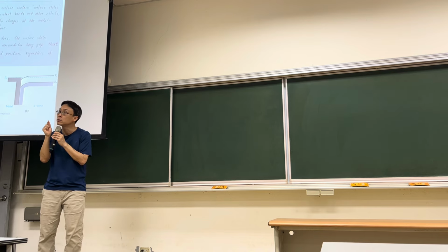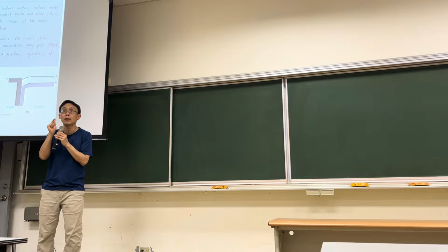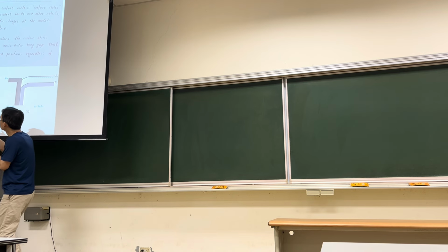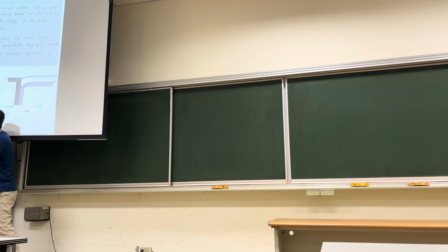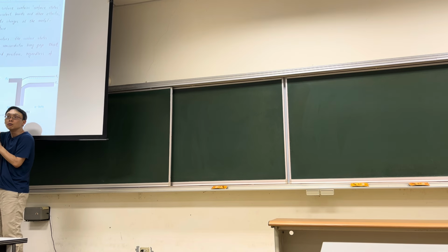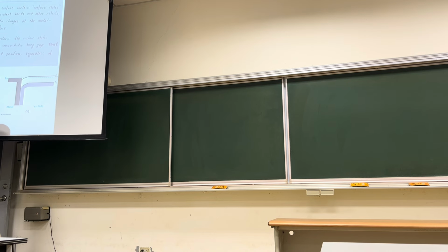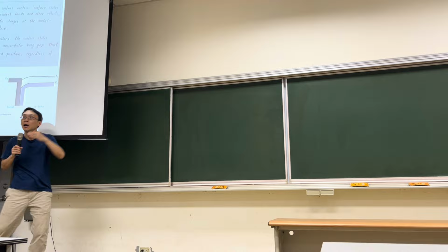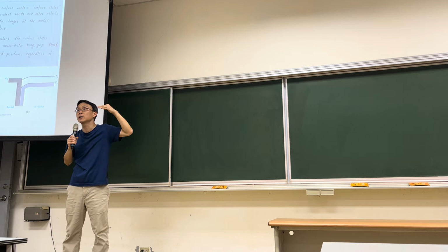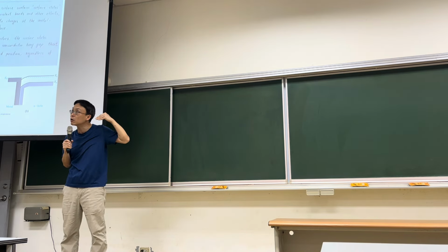If this happens, it doesn't matter which metal you choose. It always gives you a certain type of contact. It's like this case, metal and N-type gallium arsenide. You usually have a Schottky barrier because the bending is always going up due to the presence of surface defects or interface states. So usually on the surface of a semiconductor, you will have a lot of impurities.